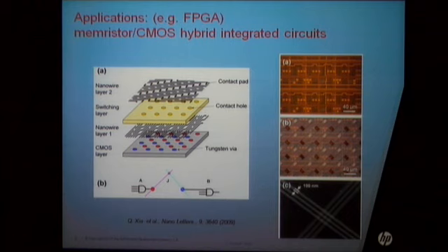If we can lift the wires and the connections from this CMOS layer and put them into another layer on top of the CMOS layer, we can put more devices in the CMOS chip, and then we can use tungsten vias to connect these two layers. So here we use a memristive layer to serve as the wires and the connections. In this case, you will have a higher device density, and the device can also be operated at higher speed and consume less power.